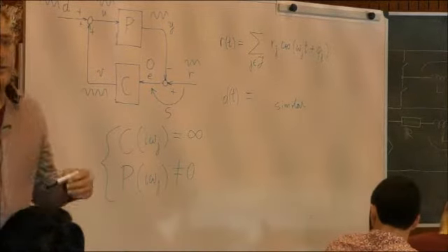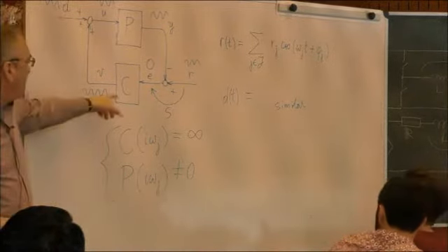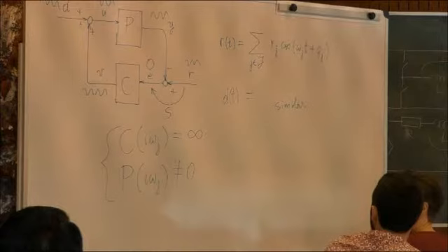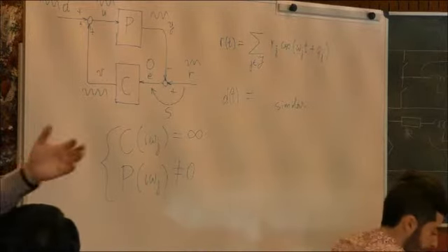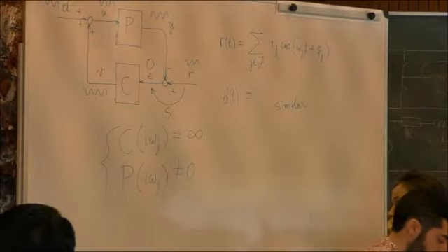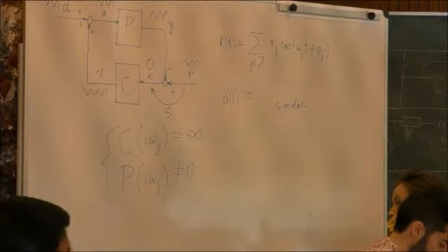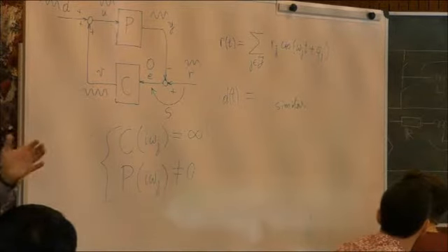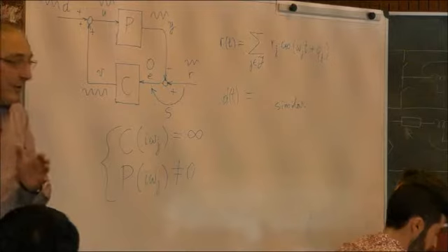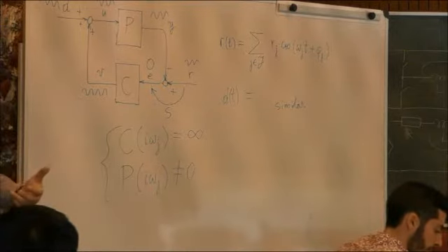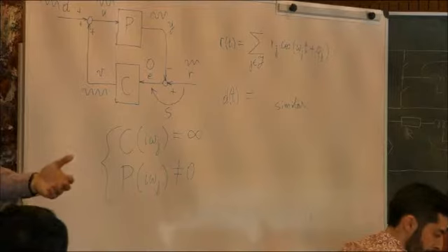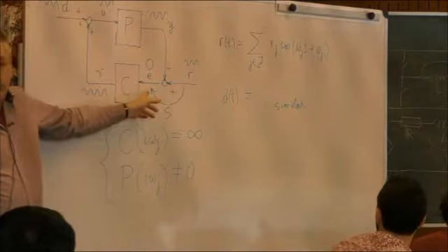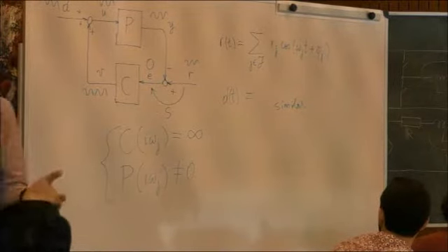And if the controller by chance deviates, let's say that at some stage, I don't know, a glitch occurs. Let's say that this is running on a processor, and the processor misses one cycle, so that's a glitch, right? Or misses 100 cycles of the processing time. Then the phase and the amplitude of the output will have a glitch, it will move. Then a transient will occur, and you have to wait again for a few seconds, and again it will correct itself, and this will become 0. So it automatically corrects any glitch.